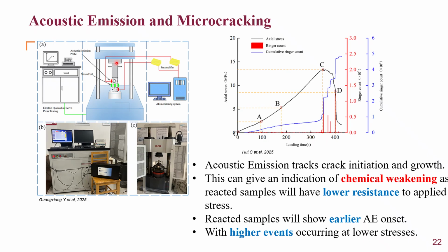As the sample is undergoing stress, these microcracks generate acoustic energies which are picked up by the sensors, amplified by the preamplifiers, sent to the collection unit, and displayed on the system for you to visualize. This is a visualization of an acoustic emission monitoring system from Guangjiang et al.'s paper.